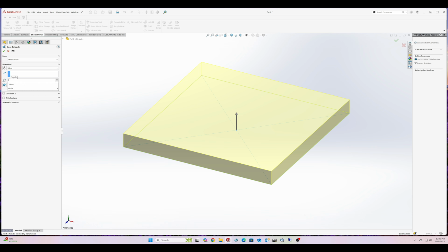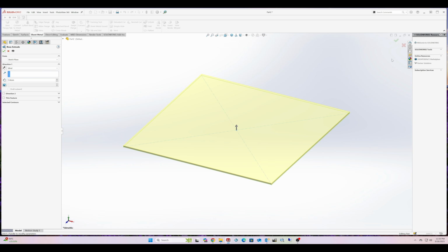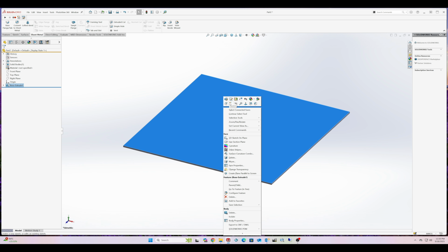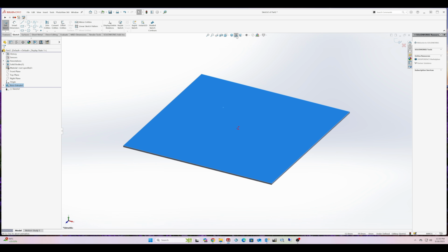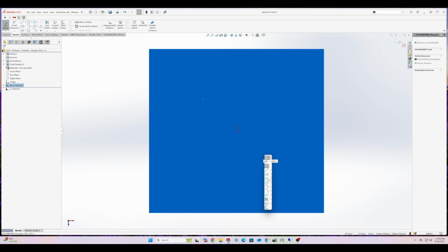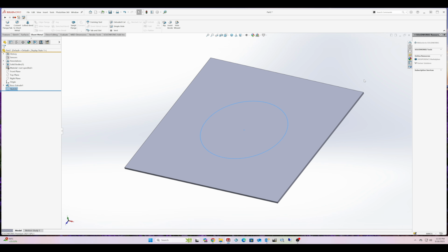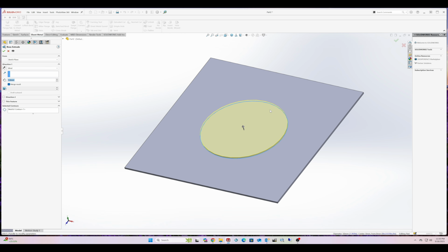So all I'm doing is taking one of my thinnest sheets of metal, and I'm going to draw it up real quick. Once I get that plate there, I can start adding a form tool to it. The reason I called it the knockout is that's one thing we use around here all the time: a knockout tool, where we'll do a 50 knockout, so that you can go in and knock that part out down the line if you need to run electrical or something through it. So I do my sketch, and I create an extrusion here.